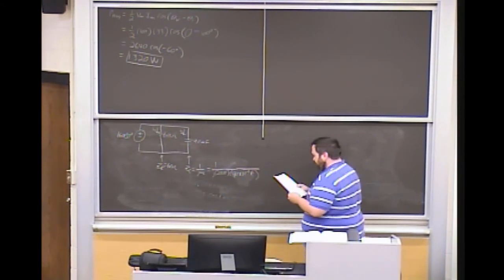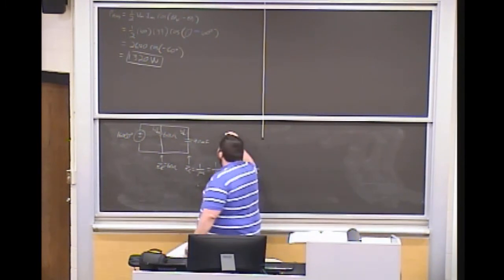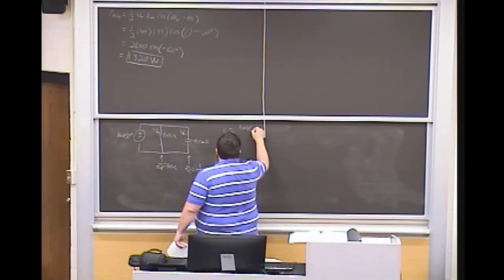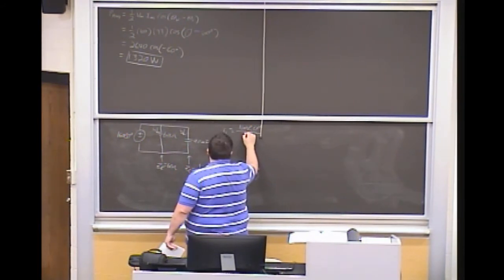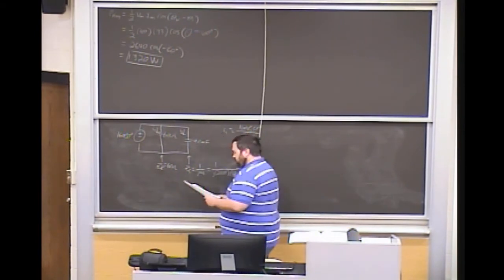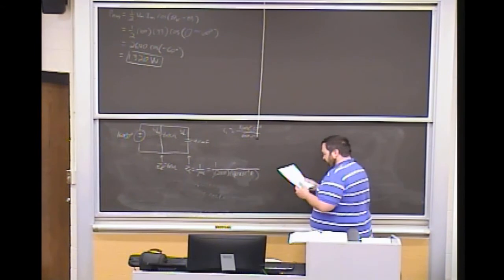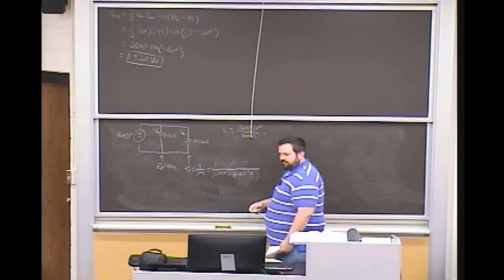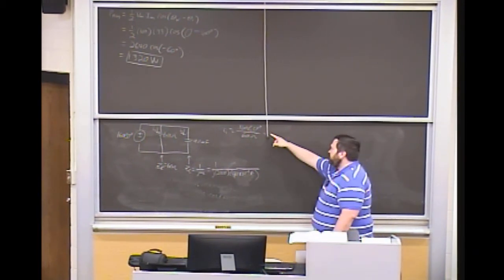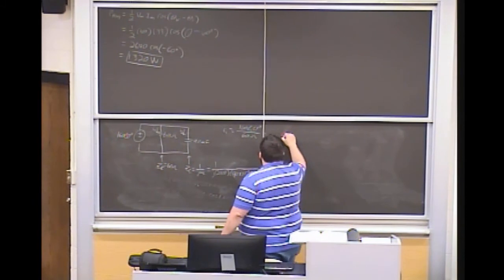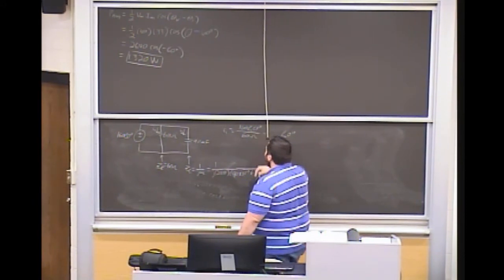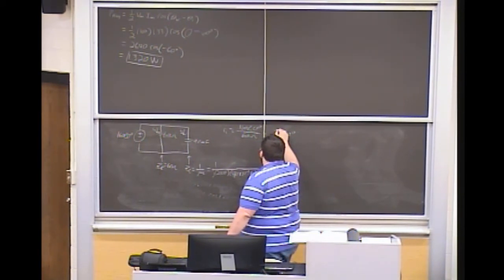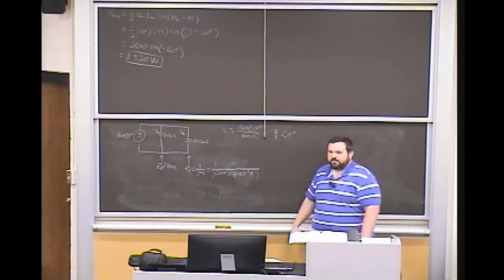Okay? And so if I do that, my I1, that's going to be the current through the 60 ohm resistor, is just going to be the voltage divided by 60 ohms. And so, therefore, my current simply works out to be 160 over 60 in there, and I'm still with a 0 degree offset. So 160 over 60 works out to be 16 over 6, 8 over 3, or about 2 2/3. Okay?